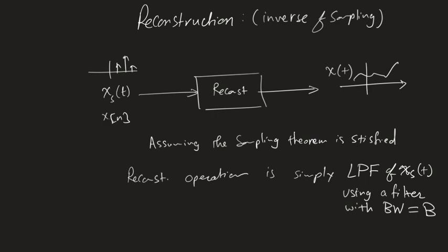But still with very reasonable quality, very minimum error, you can still recover everything correctly with what you call in engineering design a margin of error or margin of safety, right? So you design, for example, instead of saying that my filter bandwidth is going to be B, it is going to be slightly bigger than B. Instead of saying that I sampled at exactly double the bandwidth, maybe I use 3 times the bandwidth to give a little bit more space to deal with non-ideal filters and non-ideal pulses and so on. So you over-design a little bit beyond the theory so that you can recover your signal correctly, okay?